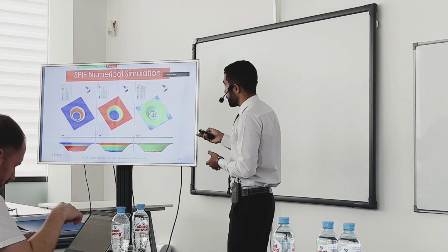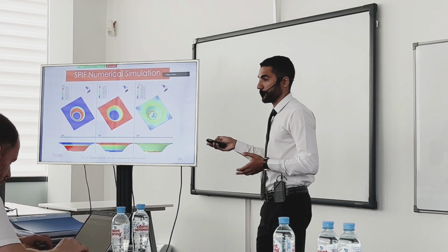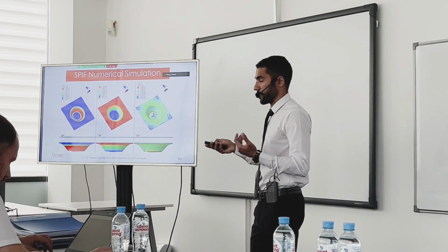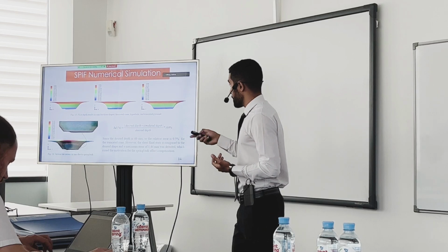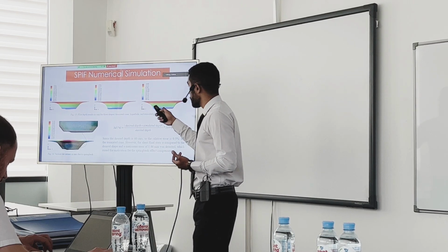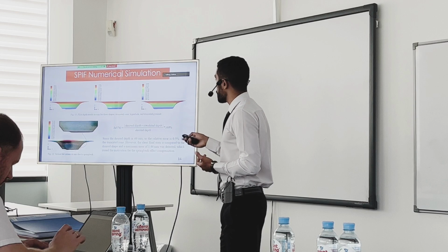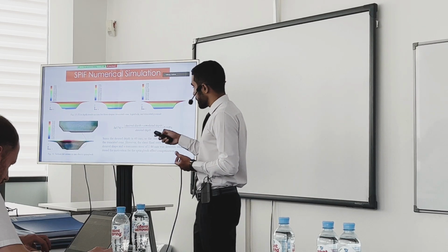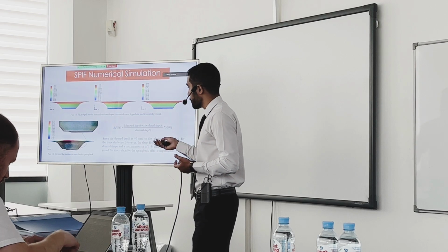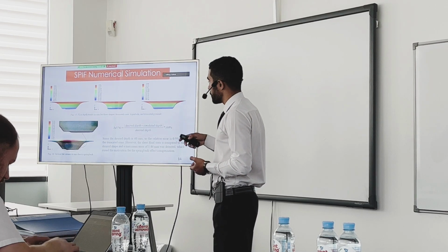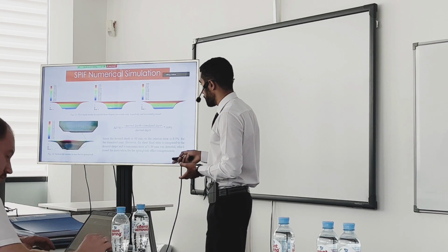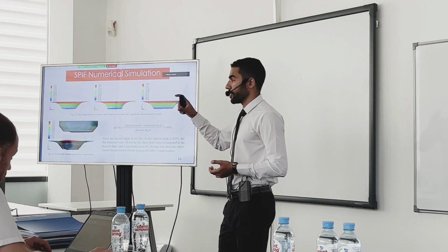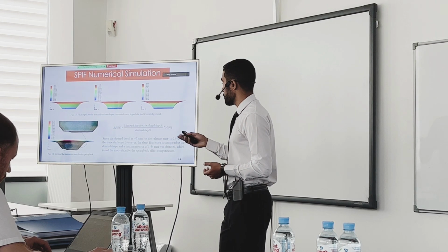Okay. So of course there were some errors in the results we obtained due to the spring back effect, which was expected, and this has been done for the 3 proposed profiles that we have, which are the truncated cone, the hyperbola, and the truncated pyramid. And in figure 16 here, you can see a visualization of the spring back effect, how it introduced some errors. For example, there were 1.1 millimeter errors in the vertical displacement. This is due to the spring back effect.